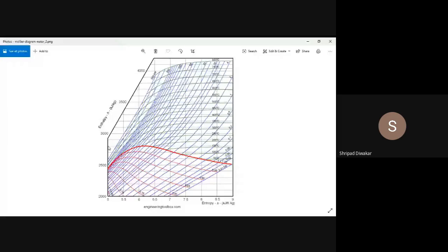So the condition of steam at inlet is 12 bar. Using Mollier diagrams, you will not get the exact value. You have to take the nearest value. Remember, if it is 18 bar pressure, don't take this one directly, you take 20 bar pressure, because 18 is nearer to your 20. If it is 15, directly you take the line in between 10 and 20. If it is 10, 11, 12 like that, you directly go for 10. Don't consider the middle one. If it is 18, 19 or 20, 21, 22 also, you take only the pressure line of 20 bar. Don't go for any other line.